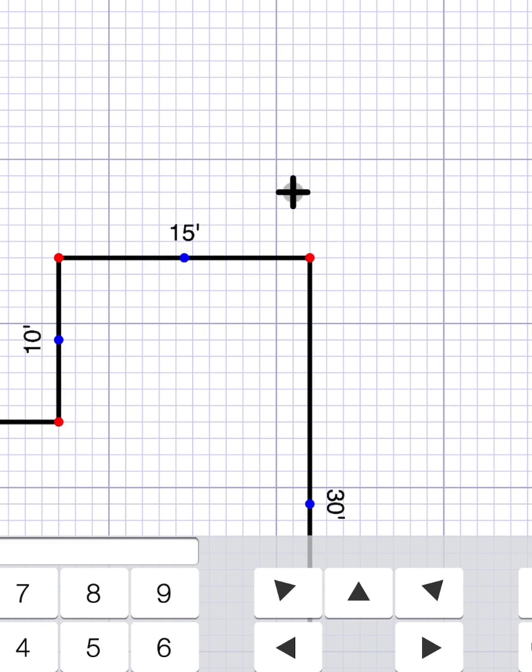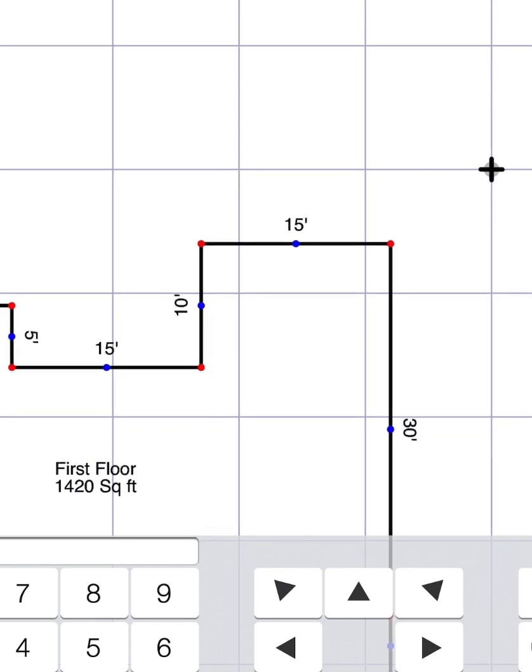Then you can go up to the end of the wall here and use your laser tool to the fence, and maybe that's 5 feet, or it looks more like 7 feet. Then you can subtract those two, the 20 minus the 5, it gives you 15. So you can do a little really simple math and still use a laser measurement tool.